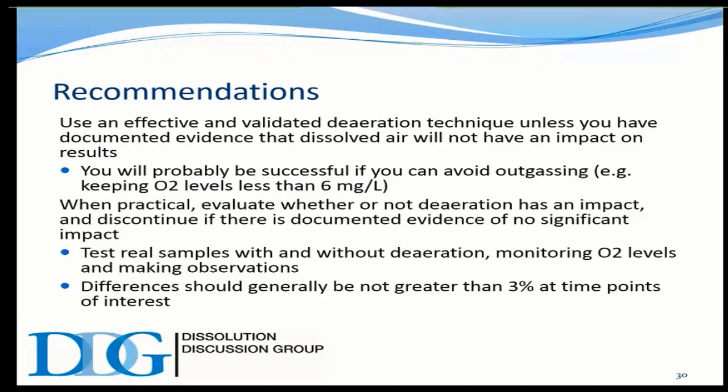But if you can keep it at around 5, and it generally does not get above 6, as we showed in that graph, this should be sufficient on controlling the amount of air that will exist within the dissolution test. So for real samples, with or without deaeration, monitor O2 levels. You should make observations like one of our guests suggested, but I would suggest that a measurement be taken for most assurance, and then validate that method so it's written into a procedure, and now all of your analysts will run that the same way.